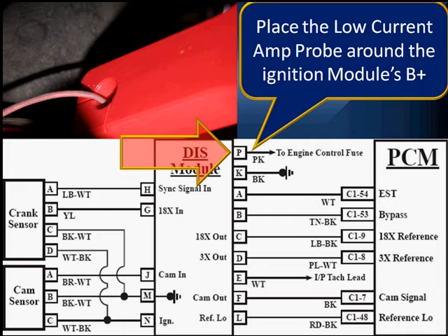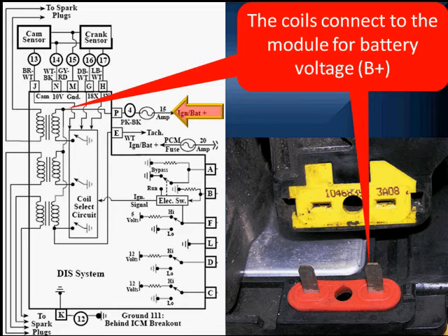We want to take you deeper than just the elementary stuff like this. Let's go even deeper into how this operates. Now, as you look down to the right, this happens to be a module that has 3 plug-in coils. There's one of the coils on how they plug in and pick up the B+ and ground supply. What we're doing is we're measuring current on this pink and black wire, in this case, coming into here.